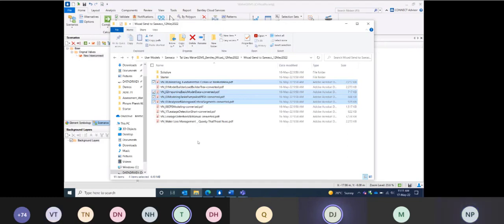And then the modelling fundamentals, where we learned how to draw a network out from scratch using the layout tools. So that's important. If you need to add anything to your existing network, you need to know how to use the drawing tools. And then of course the valving in critical segments, which I think is, we have a lot of features in WaterGEMS, which of course you can see in the analysis tab, but criticality is one of the best, and the reason I think it's one of the best is because it's very, very simple and quick to use, but you also get a lot of fantastic information out of it.